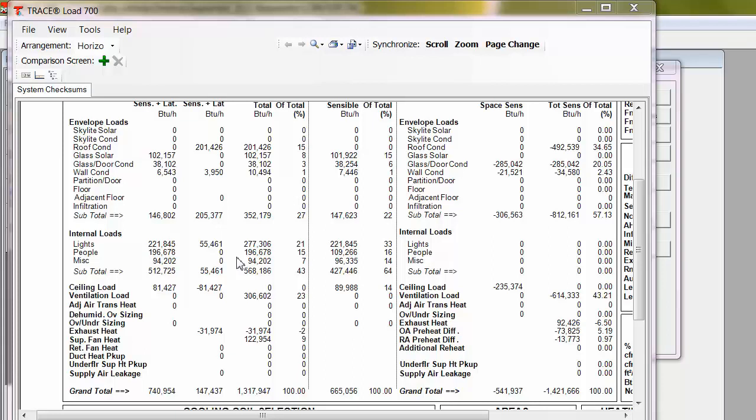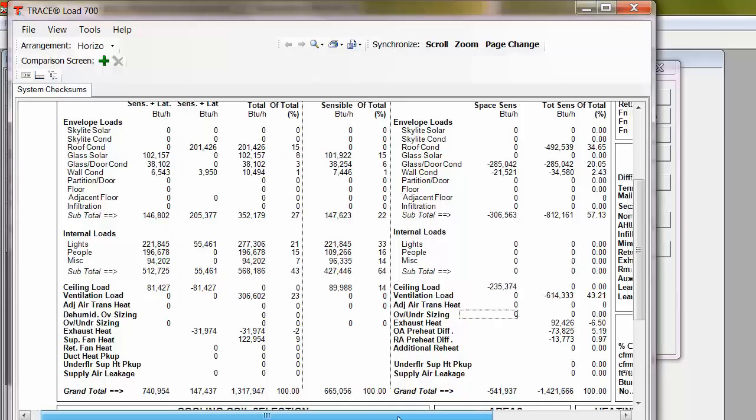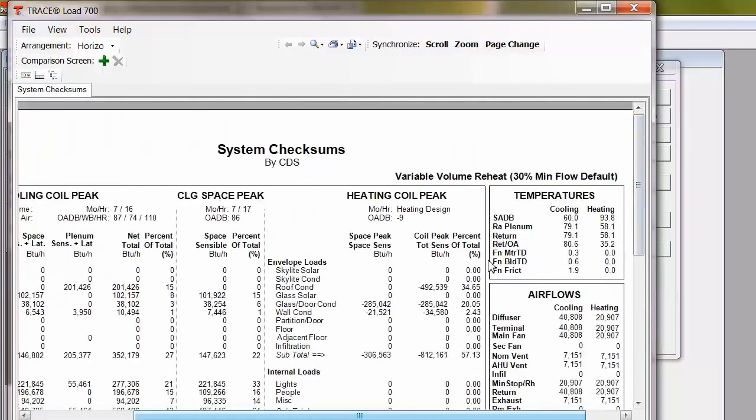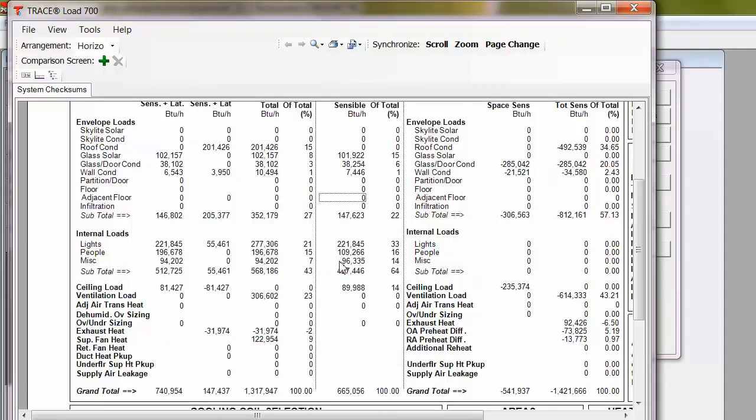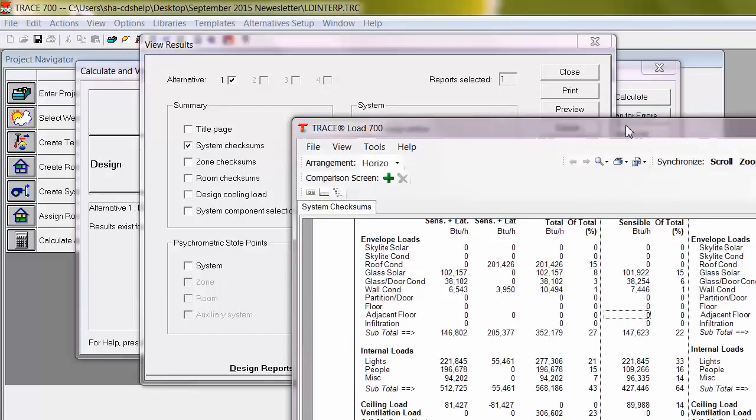If we were troubleshooting, let's say, extremely high airflows or even high fan energy usage, we can first start here and see what is driving the high airflow. Is it the load? Is it the supply air dry bulb, which is reported in the top right-hand corner? All the information about the design of our system, as well as the building loads, are shown all in this report. Additionally, from an input standpoint, we can see drastic changes in results by the scheduling of internal loads.